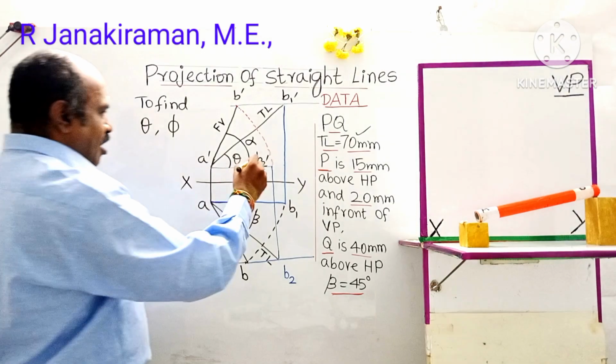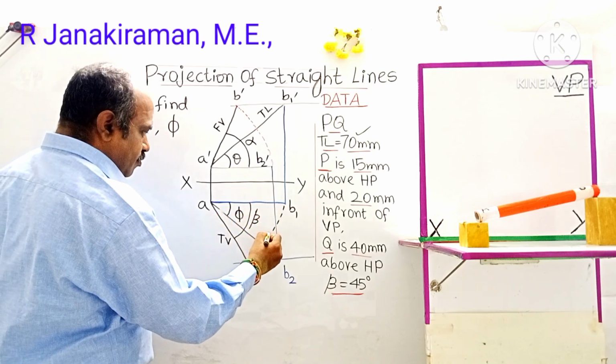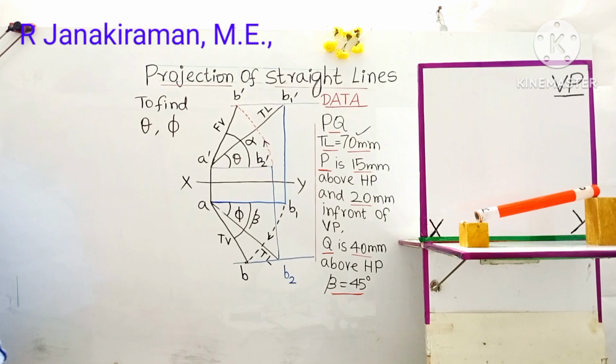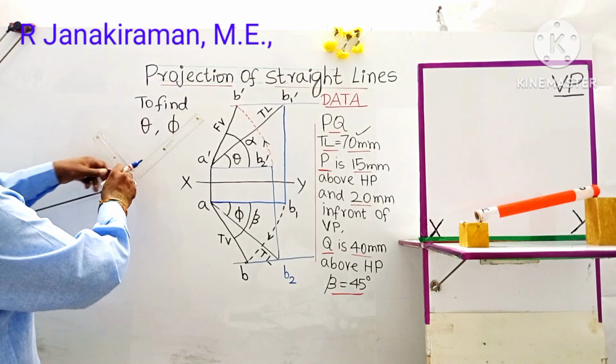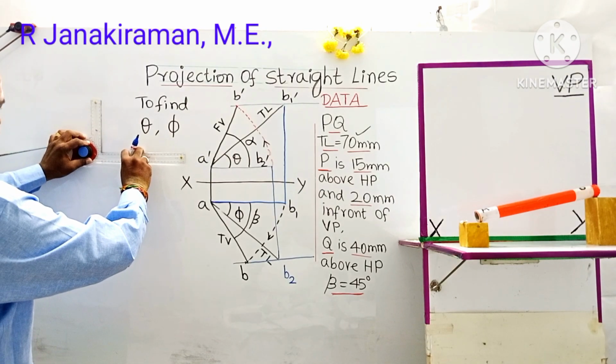Okay, so this is the arc drawn upward. This is the arc drawn downward. Okay, these are the usual notations followed. So take a drafter scale and draw the far diagram. Release the nut of the drafter. Look, set your drafter scale horizontal.